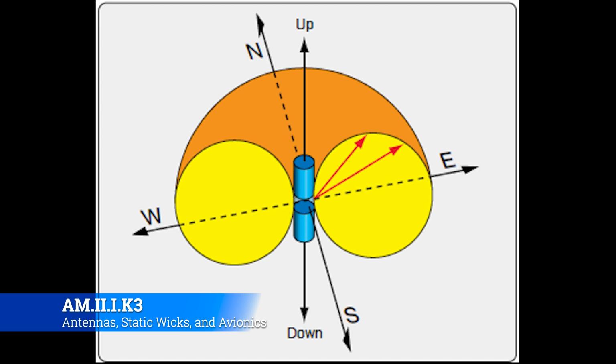Now, why and how does it matter? Well, in this particular case, with this omnidirectional antenna, it really doesn't matter that much. There are a couple of implementations you might be able to use in flight, but it would be very, very slight even if you did. For the most part, it's inconsequential. However, when you start getting to specialty antennas or certain types of antennas, that can make a big difference. You can design an antenna so that it is optimized for the person or the people that you think you're going to be reaching with it.